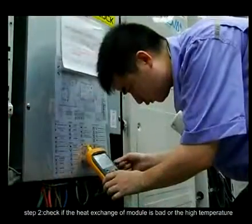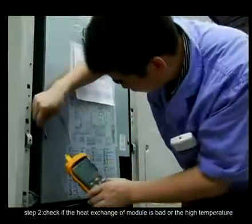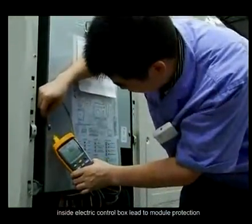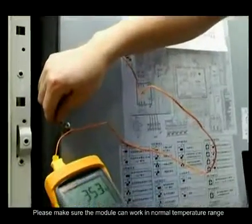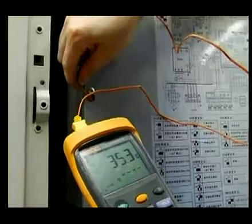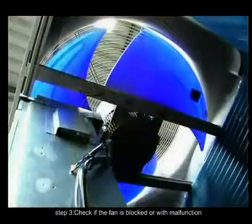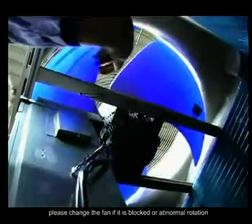Step 2. Check if the heat exchange of the module is bad or the high temperature inside the electric control box leads to module protection. Please make sure the module can work in normal temperature range. If it is normal, please go to the next step. Step 3. Check if the fan is blocked or has a malfunction. Please change the fan if it is blocked or has abnormal rotation.